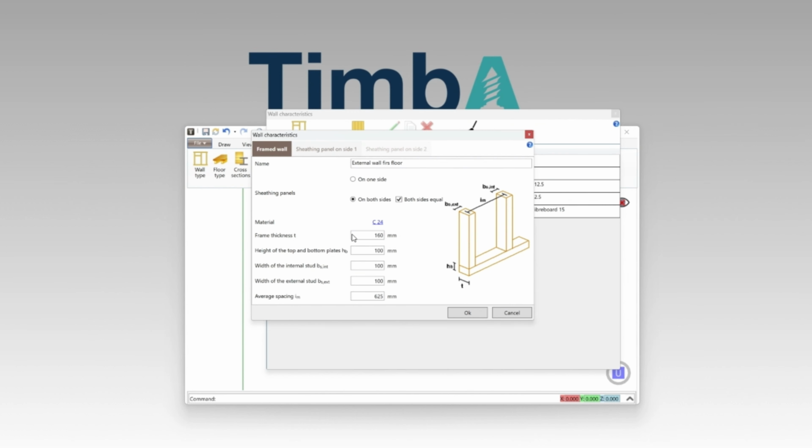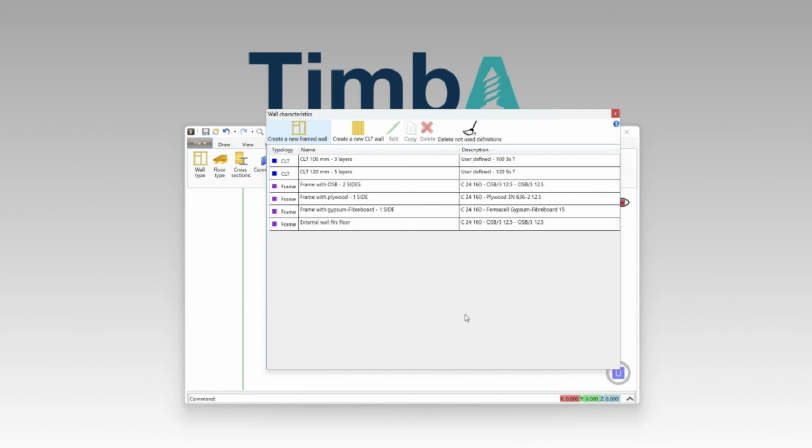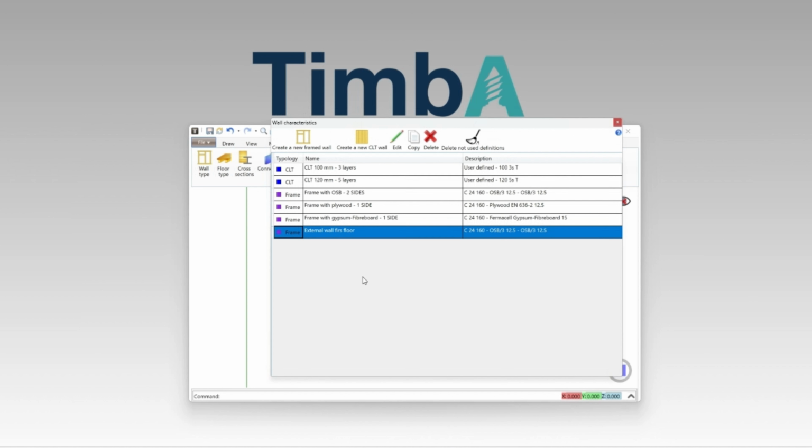Once you've selected the material, enter the rest of the details. Frame thickness, wall height, wall width, and average spacing. That's it for the external wall, now ready to be used in the design. You can follow the same process for internal walls, especially if they have different materials or configurations.